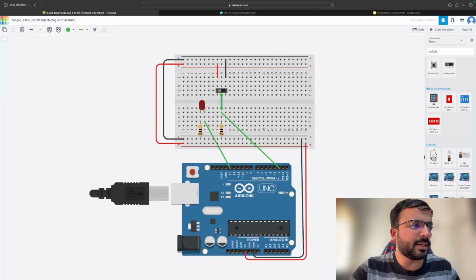I'll be reading from this middle, right? And I connect a resistor to it to avoid any high current or anything like that which breaks the switch. Now I told you, one plus terminal of this switch is connected to 5 volts, and the other terminal is connected to 0 volts, and whichever side the pole throws to, right, it's a double throw.